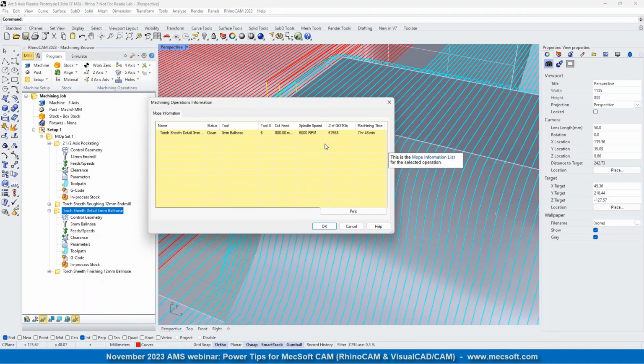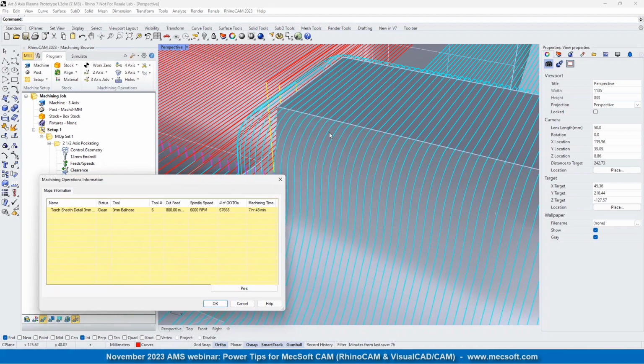So that just demonstrates how your tolerance can affect your toolpath. It affects your generation speed, simulation speed, machining speed, and your surface quality. Again, a higher tolerance will be less accurate, so you may see faceting in the surface you're machining if you have a tolerance of 0.1 versus a tolerance of 0.01.